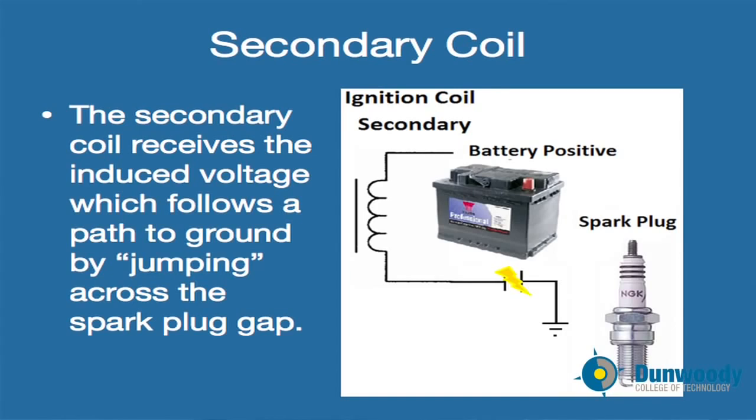This follows a path to ground through or by jumping across the spark plug gap that's included within the spark plug itself. That gap can range from anywhere from 30 thousandths of an inch up to 60 thousandths of an inch, and when worn out, can be even more.